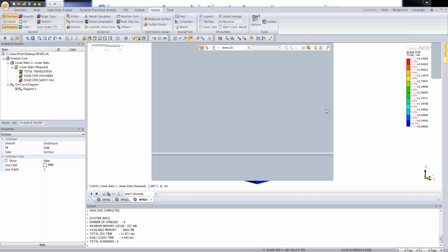So if we want to use the force, usually the direction of the expected deformation or acting force direction should be free. Let's say displacement is itself a constraint. It's actually the same definition, because constraint is displacement with the value of 0. So from the numerical point of view it is actually the same. So there is no need to constrain the displacement in NFX.